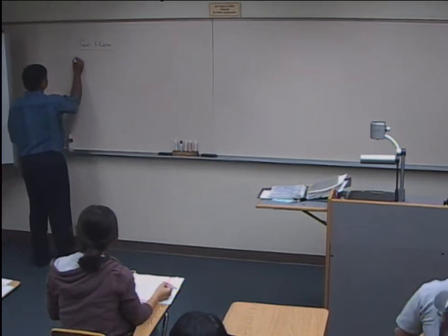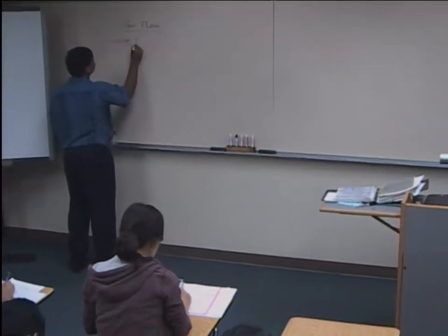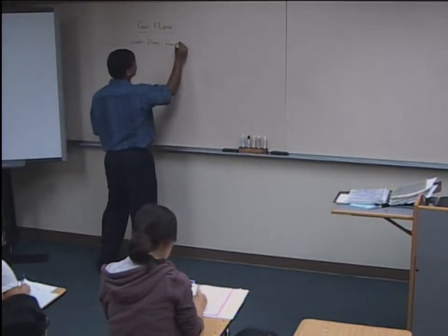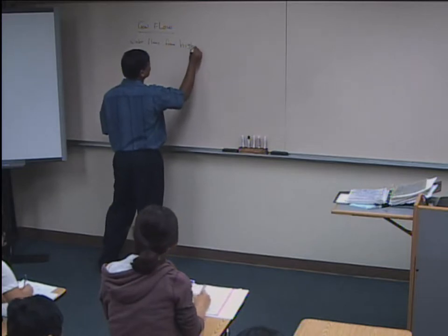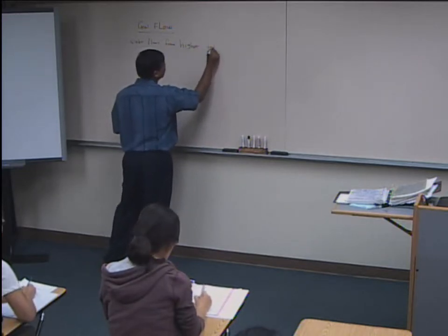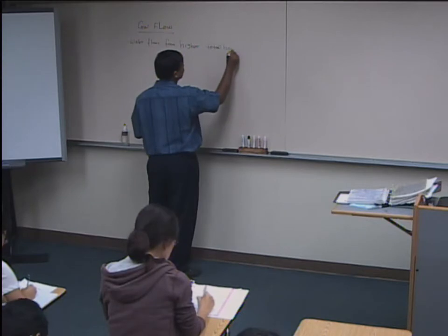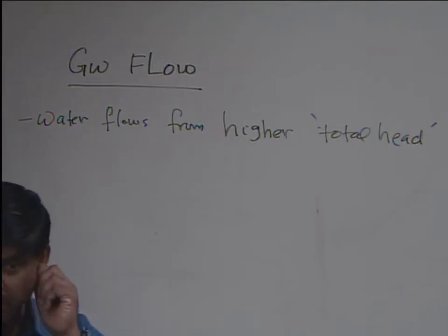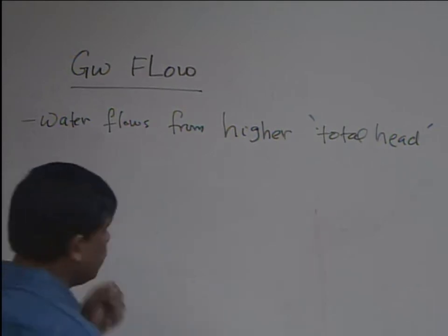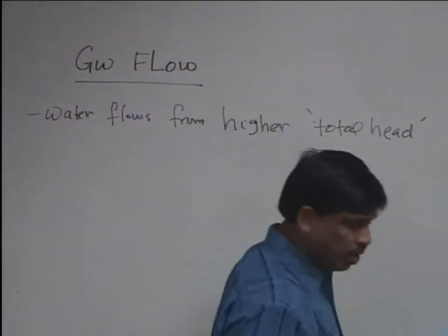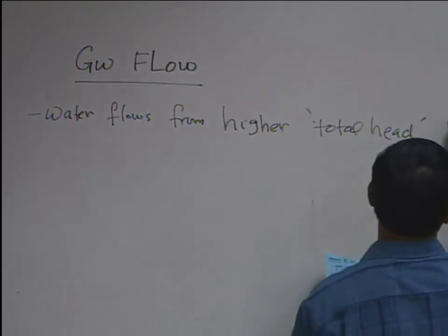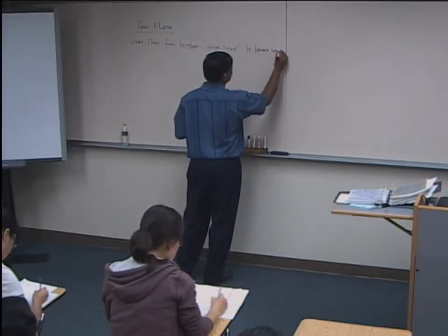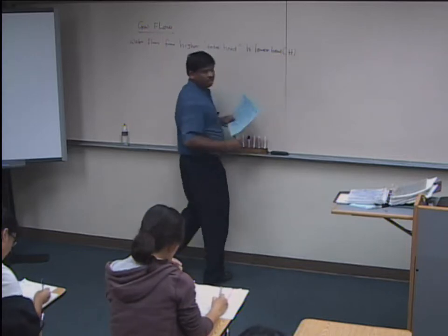Water moves according to total head, not higher pressure head. Water does not move from high pressure to low pressure. That's a wrong statement, actually. It goes from higher total head to lower head. And we're going to indicate head as this big H.